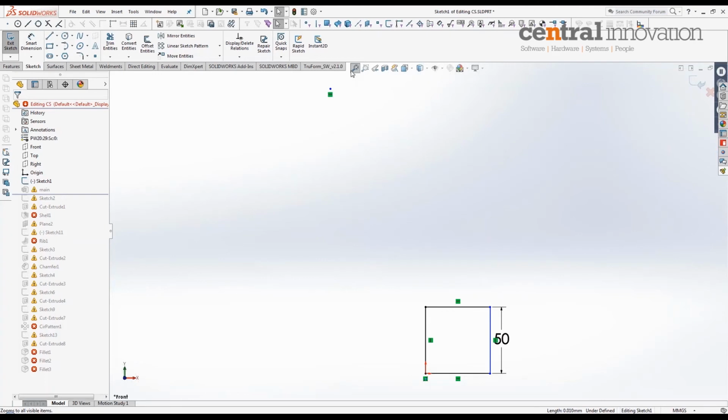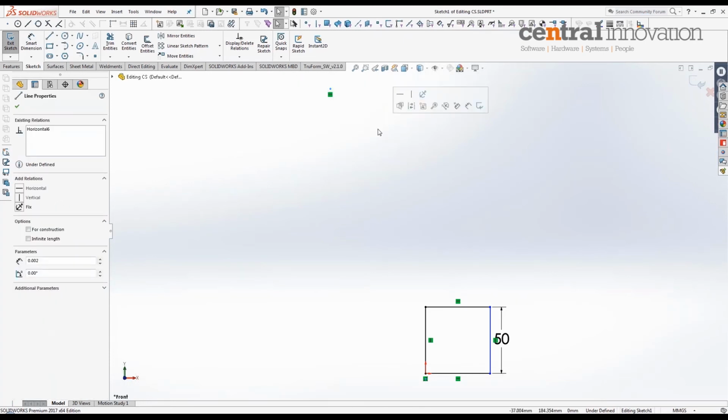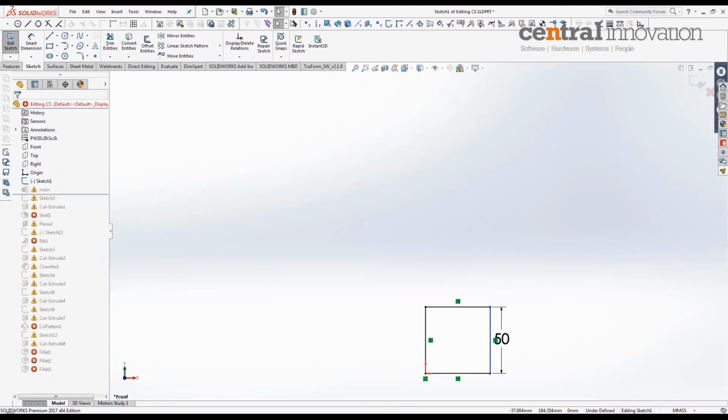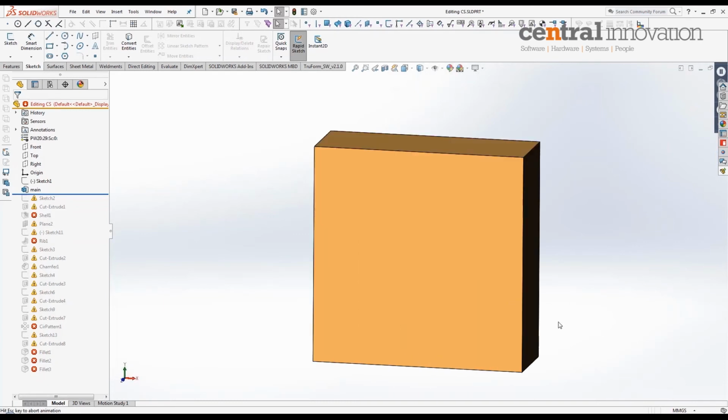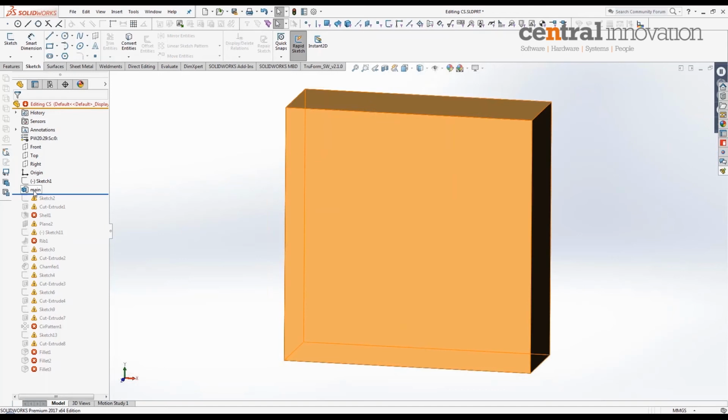and I immediately notice there's a sketch entity which had been created far away from the origin, and most likely it's an unintentional action. So basically I'm going to draw a rectangle around it to select all the entities which I don't need and hit the delete key, and the moment I exit my sketch, you will notice extrude both feature is now created properly without an issue, and also the main feature does not have an error attached to it anymore. So that is essentially solved.